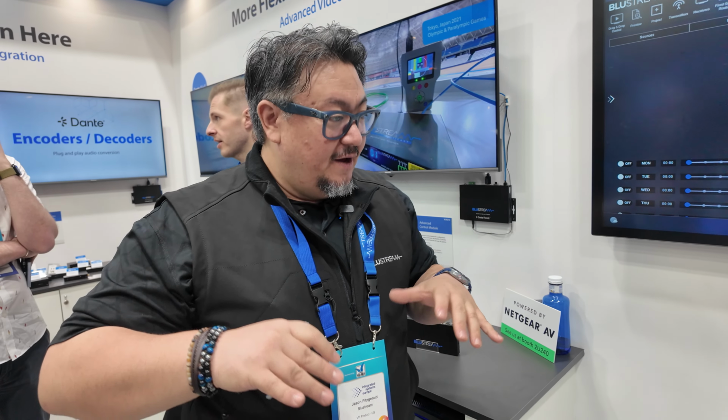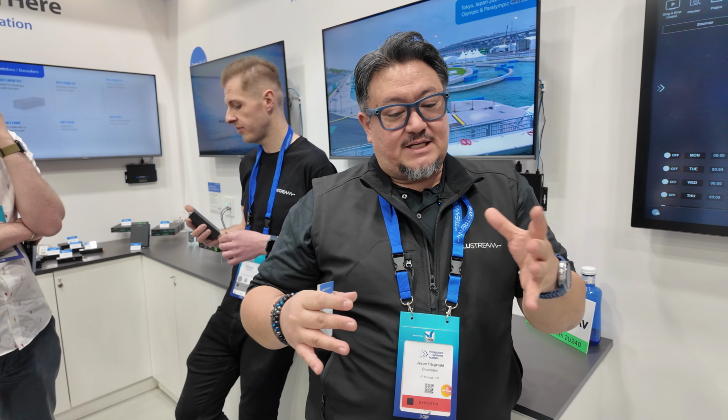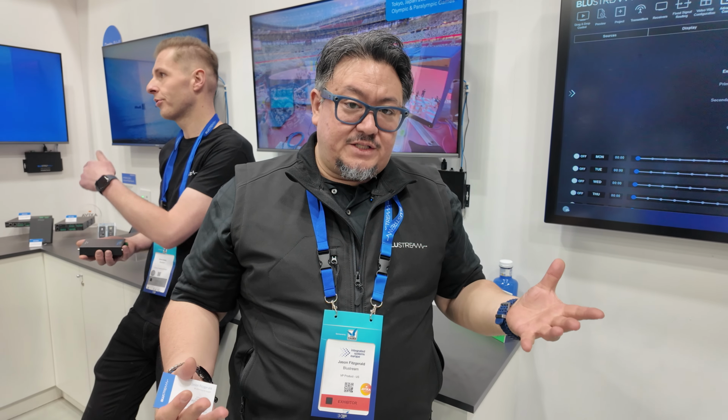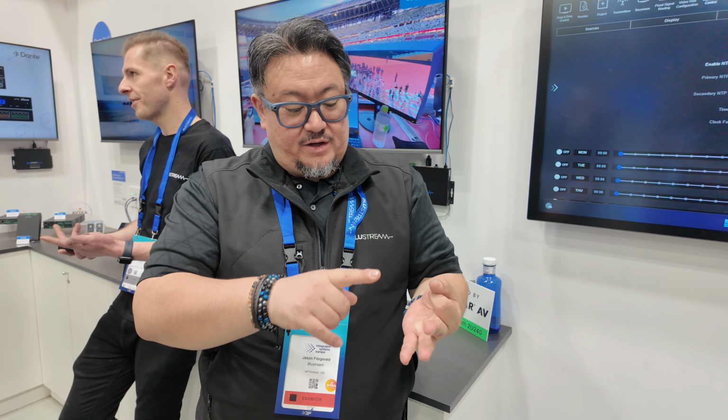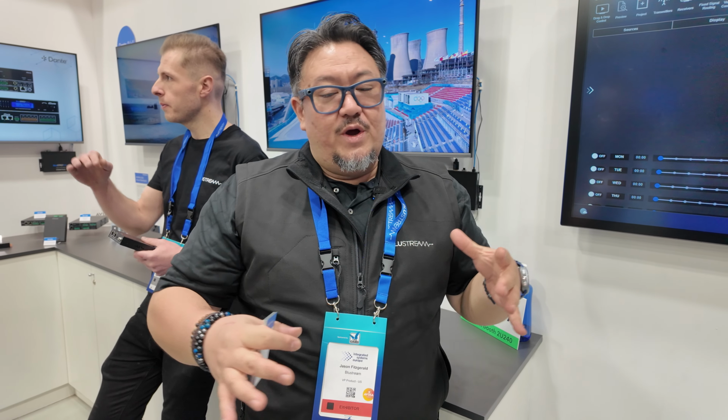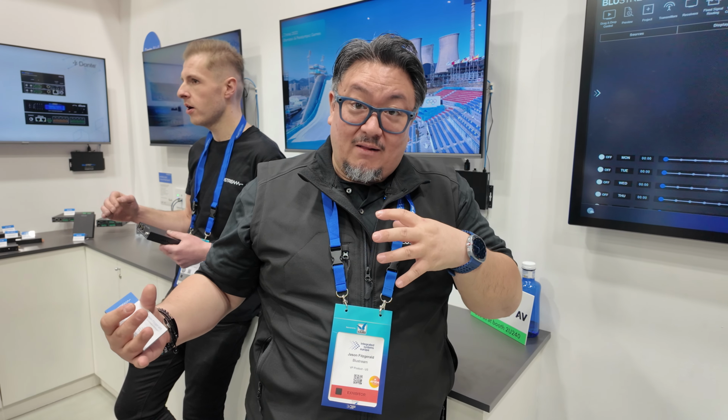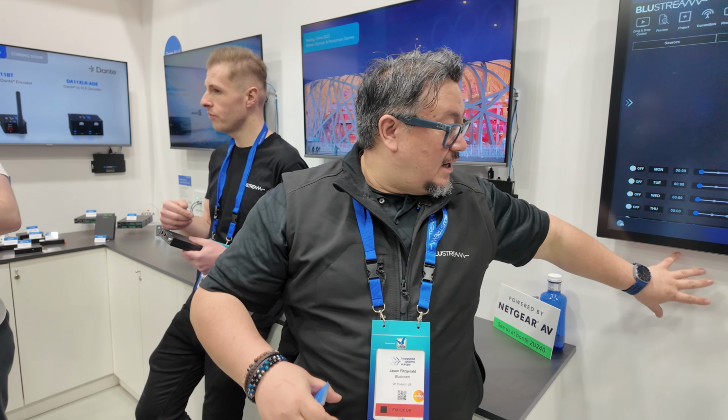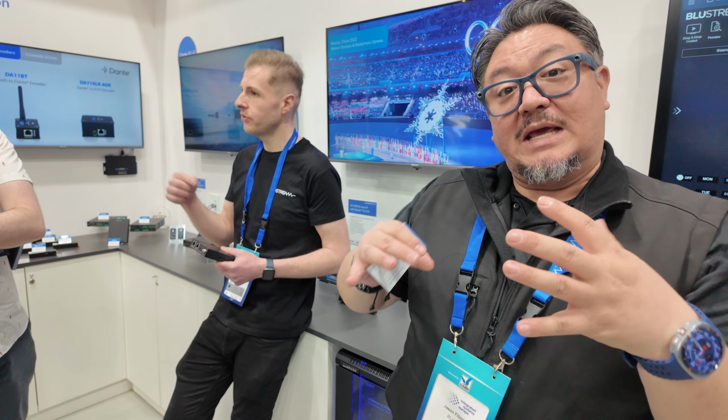Now the 300 series, very cool. The 300 series takes us from 4K 30 to 4K 60. So the IP300 will allow us full 4K 60 444 on a 1 gigabit network. The 300 series gives us all the same controls: IR, serial, CEC, USB capabilities. We also have a brand new wall plate as well. Now that wall plate transmitter is something that's been really asked for. It allows us to basically set up a wall plate. We've actually got it sitting over here to be able to input HDMI and USB-C, the first USB-C input, directly into our system from a wall plate. And it'll auto switch between those two inputs, or set it up manually, right?